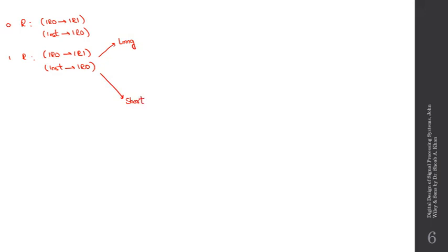So in case of a long instruction, the data from IR1 was fetched to the decoder, whereas the data from IR0 was fetched into IR1, and the data from the instruction was fetched into IR0. Interestingly, the last 2 steps are the same as the ones which we took at read number 2. This means that if we consider them as states, whenever a long instruction occurs, it's similar to the state that was occurring at read number 2.